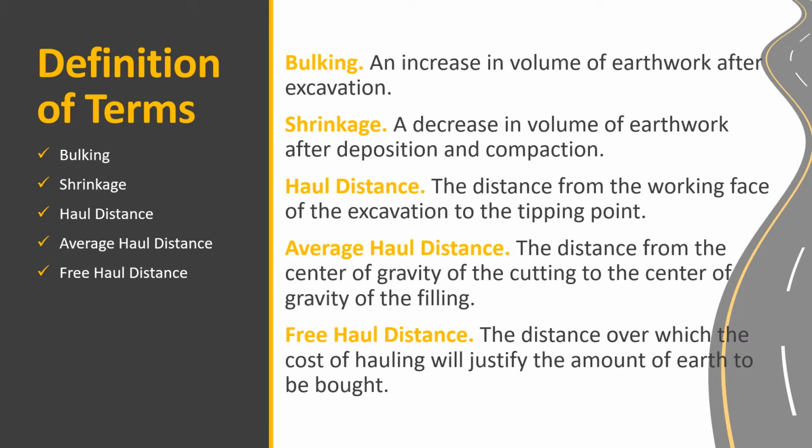So it is important to determine yung free haul distance, para alam mo kung hanggang saan yung limit ng distance, kasi hindi naman pwede na sa malayo ka kukuha ng soil kasi that will be costly. So in hauling earth material, you will also consider computations on distances para mas economical yung magiging project or yung pag-haul ng soils.